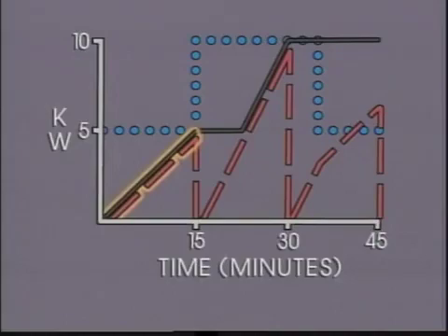This is the maximum demand, or average power used, during the first interval. At the end of the interval, the pusher arm reset back to 0 so that it could begin measuring the average power used for the next interval. The pointer remained at the 5 kilowatt indication to provide an indication of the maximum demand up to that point in time.